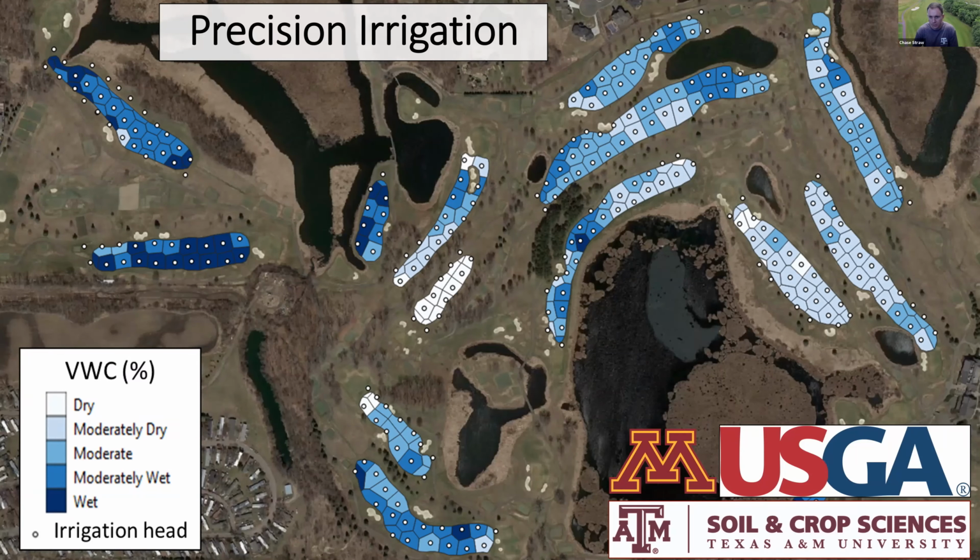So if you have individual head control, you can program your system, for example, all the heads with a wet soil moisture class, to irrigate together, and then do that for each of these soil moisture classes. And then once you've reached a certain threshold based on the in-ground soil moisture sensor for that class, you only irrigate those heads that night. So it removes the chance for overwatering.